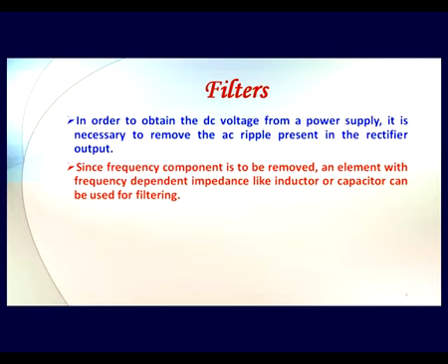Also, if you remember, in the rectified output the signal goes from 0 to V maximum and comes back, then again goes up to V maximum and comes back. So it is a kind of sinusoidal signal only, which varies from 0 to Vm, the peak amplitude of the input signal. Now when we want a DC voltage at output, we want the output of our circuit not to reach 0 value, but to remain at the average value, typically near the DC component of the rectifier output.